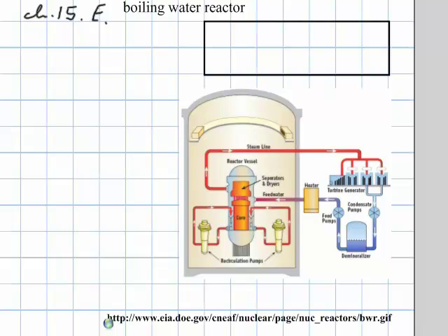The plant operates at 3/4 of its Carnot efficiency, and the electrical output power of the plant is 1.2 billion watts. A river with a flow rate of 100,000 kilograms per second is available to remove the rejected heat from the plant. Find the number of Celsius degrees by which the temperature of the river rises.